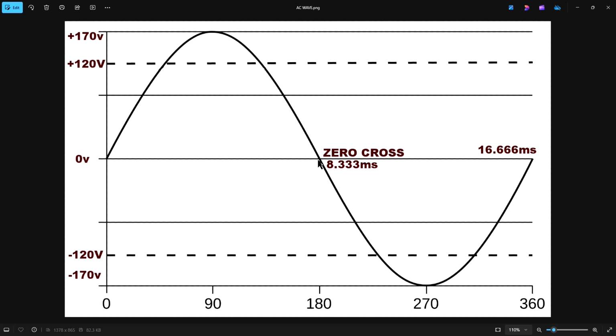If I did a pulse, it would stop. There'd be no voltage on the gate at this point. It would turn off because it is not conducting any current, and it would be off again. We would start off across here. That means that we can only control the turn on. If we turn one on, we have to wait till we get to a zero cross before it will turn off on its own. We have no control of that. So that's an important point to understand to go into the next thing we're going to do.